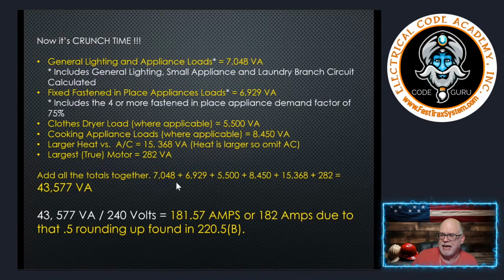And it's okay. In the 2023 edition, you have a nifty little table, and I think in the 2020 as well. Prior to that, you had to go to Informative Annex D, under the D7 example. But it's basically called the 83% rule, and it's 83% of what's marked on the breaker or fuse rating.